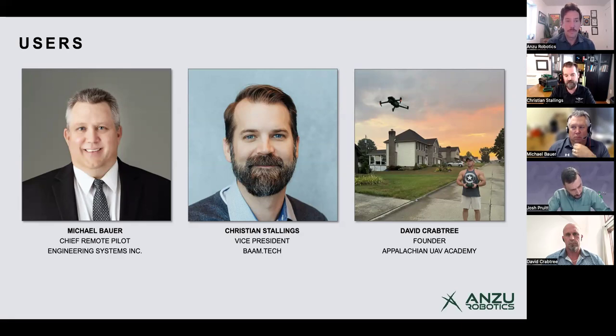When it comes to building projects, I know, Michael, you mentioned some challenges with Pix4D. A lot of our workflows for photogrammetry, we're often utilizing and recommending Metashape by Agisoft. And everything came in. It was able to read all the XMP data in the imagery perfectly fine. So it had all the position, it had the accuracies, it had the orientations from it.